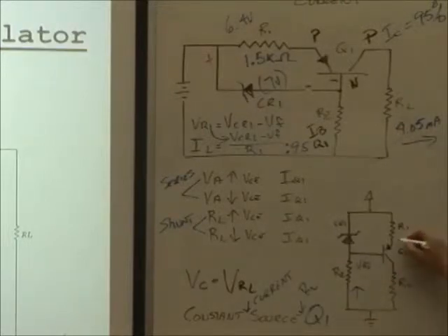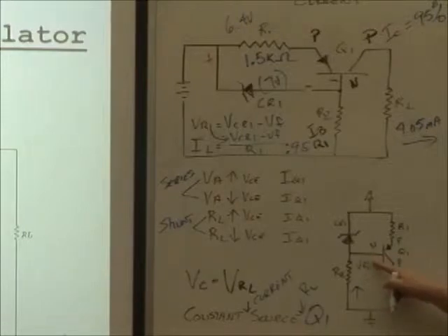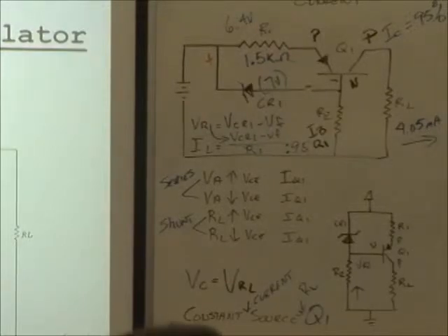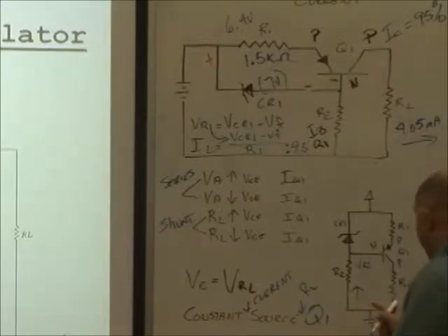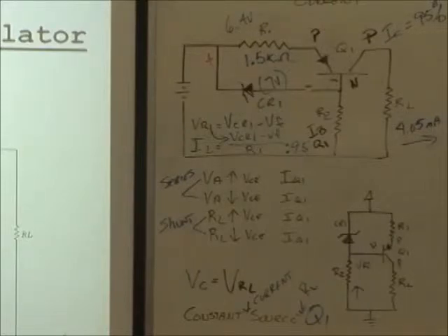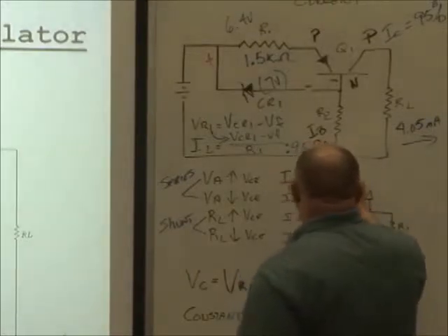what type of transistor? NPN. So if I apply a larger potential on the base, which is N-type material, what's the transistor going to tend to do? It's going to conduct less. And look, there's the proof right there. The base voltage increased a little bit, didn't it? Yes, sir. So it's going to conduct less.